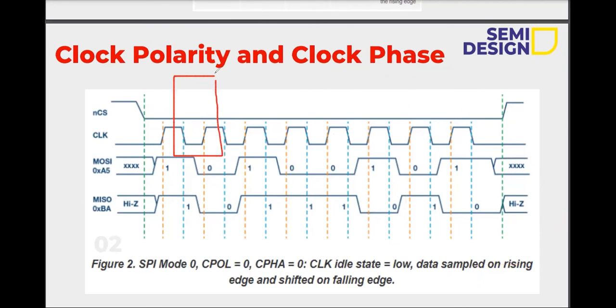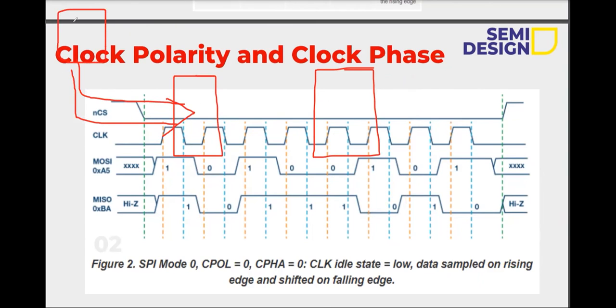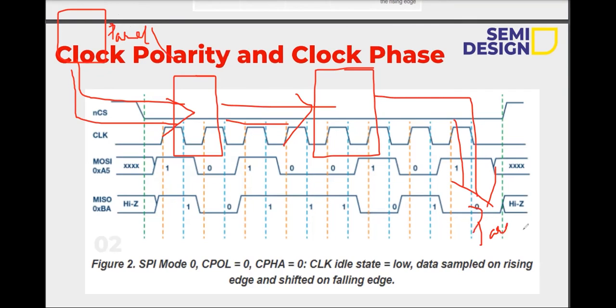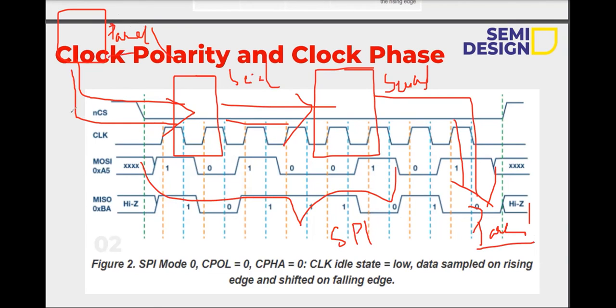What is meant by protocol? This is one component and this is the second component. Whatever data we receive from a previous component or some previous circuit, some processor and so on, we are transmitting to the overall motherboard. But here this processor may be accepting parallel data, and here it is accepting parallel data, but these internal components may not accept parallel data. They may accept only serial data. For that purpose, we take the protocols and convert the parallel data into serial. Here we are using the SPI or I2C protocol for these communication purposes.